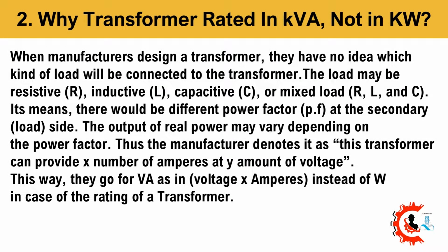2. Why is a transformer rated in kVA, not in kW? When manufacturers design a transformer, they have no idea which kind of load will be connected to the transformer. The load may be resistive, inductive, capacitive, or mixed load. It means there would be different power factor at the secondary load side. The output of real power may vary depending on the power factor.